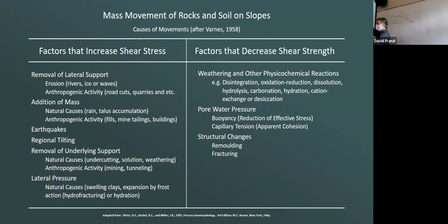That's why we can get over-consolidated clays in the vadose zone, because it's alternately wetting and drying and wetting and drying, and that pulls those particles together and over-consolidates them. Remember what over-consolidation is? Good. That's a good thing. And then structural change. Yes, you got to change the structure of the soil, so that makes sense too.